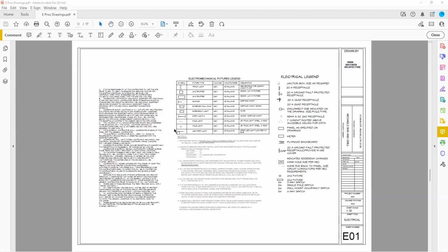Every set of plans that has a spec lighting package of some kind, or most commercial jobs, are going to have a light fixture schedule. A lot of high-end custom home residential jobs are going to have a light fixture schedule. You want to come here when you want to look for a symbol and identify exactly what type of light it is. Sometimes there's symbols and you have no idea what it is. Maybe you can tell that it's on a wall or in a ceiling. But if you come here, it's oftentimes going to tell you what the fixture type is.